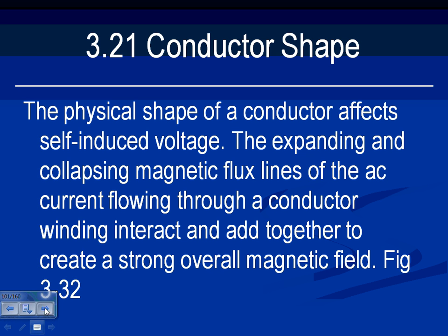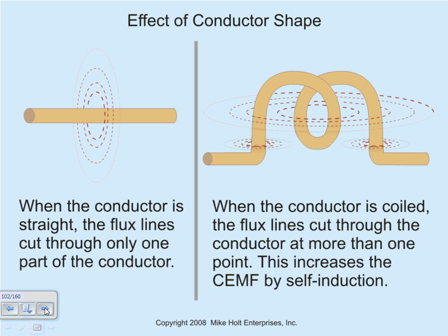Why would it transfer from the steel to the aluminum if it stays within the steel strand? It would not transfer. The main reason for the steel is we care less how much the steel is going to carry. It's there to carry the weight of the conductor. I'm just talking about the properties of it. And in the steel, because of the skin effect, the current will be carried by the surface of the steel, not the core of the steel. But your question is, why would it jump from the steel wire into the aluminum wire? It wouldn't.